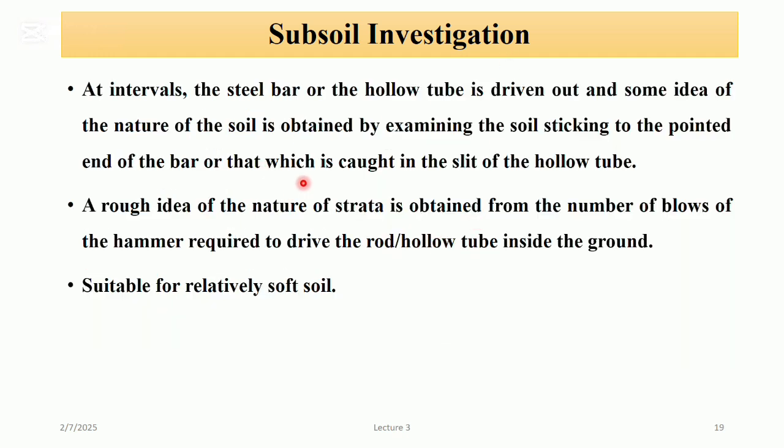This method is suitable at sites where the soil is soft, like clay, gravel, and sand. With the help of this method, it is only possible to examine the ground for a maximum depth of 3 meters.